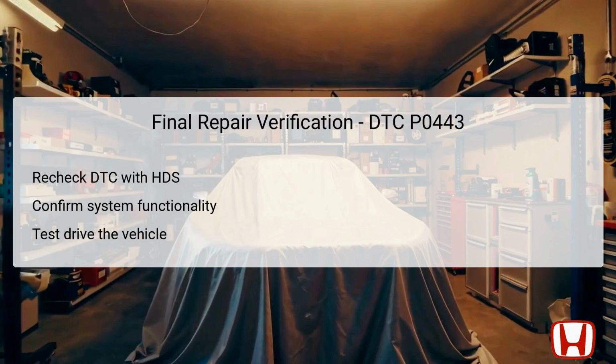After completing the necessary repairs or replacements, it is crucial to conduct a final verification to ensure that the issue has been resolved. Utilize the Honda Diagnostic System, HDS, to recheck for any existing DTCs. A clean bill of health, indicated by the absence of DTC P0443 or any other trouble codes, validates that the repair was effective.